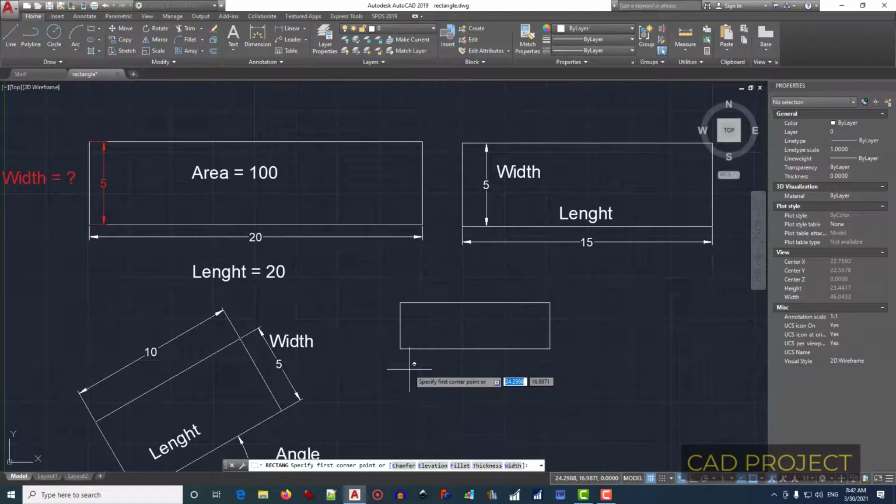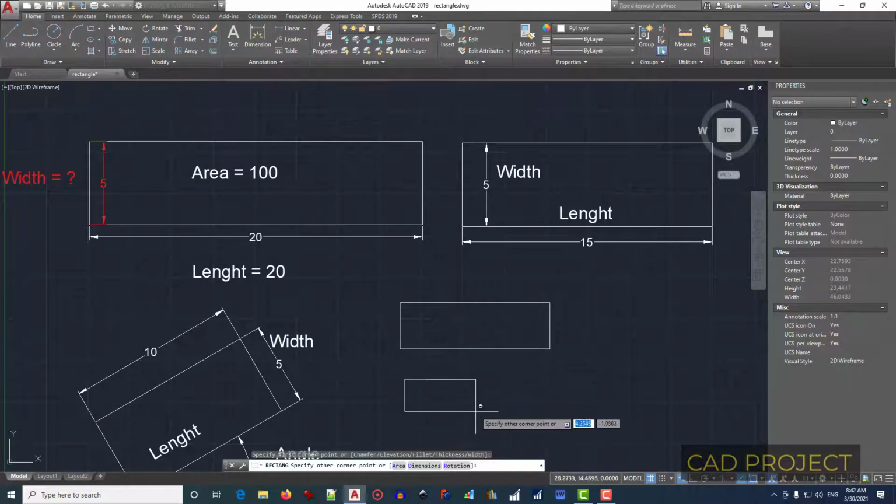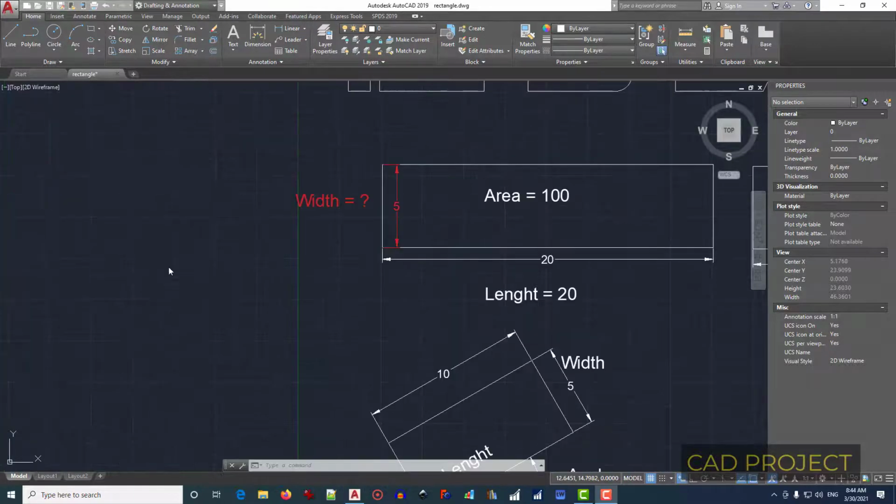As we specify a rectangle, down in the bar we have some options, and when we click for the first corner of the rectangle, we have another three options. And let's focus on these three options we have at the beginning. Now let's focus on the first option. We can go in Home menu, Draw, and select rectangle, or just type REC, press enter.